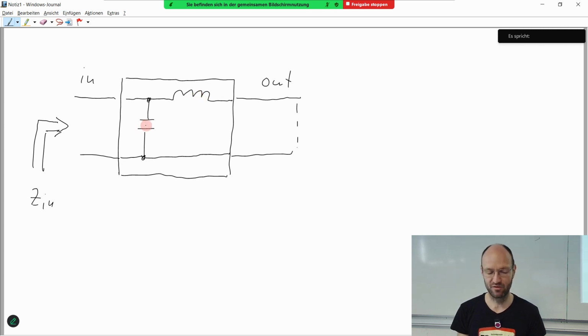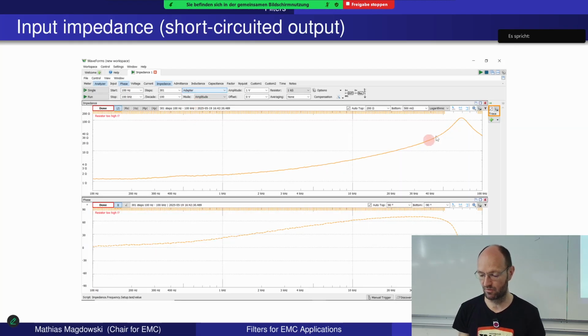So it will be easier to go through the capacitor. So we see the impedance of a parallel connection of capacitor and inductor. And so this is also the impedance behavior of a parallel resonant circuit. And so we could also think about this resonant frequency here, for example.